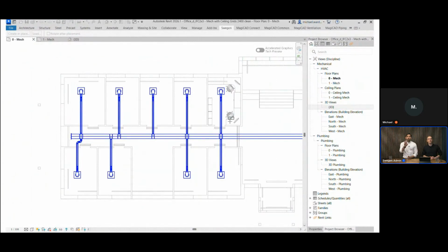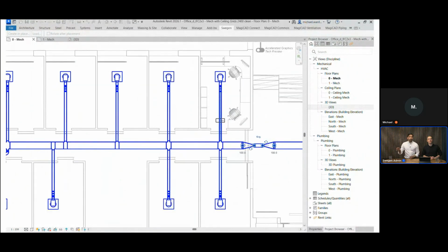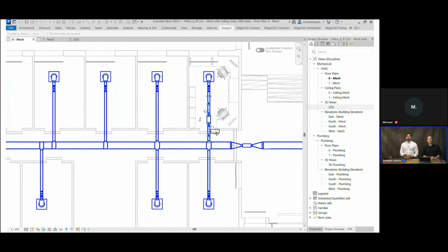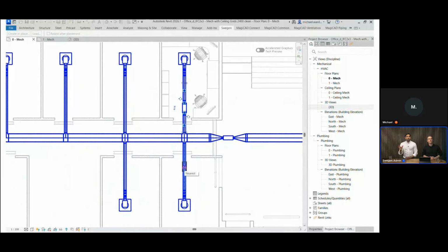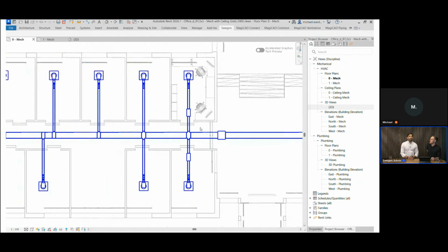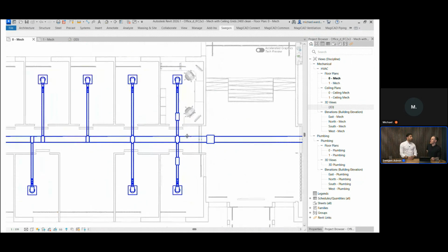And there you see you have the little silencer icon on the mouse cursor, and you can click that and drop that into duct as many times as you want. It will always drop from that range that you've selected. Into duct wherever. It drops it in, and first of all, it changes the ductwork to suit the silencer. But then if you want, and this is something you can change in the settings, you can make it so it automatically changes the silencers to suit the duct. So it picks from the range, picks the right size silencer to fit the particular duct that you want, and then updates it. And that is the family.